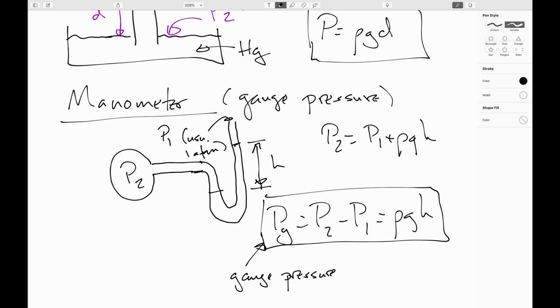Again, that's still a positive absolute pressure because it's impossible for absolute pressure to be less than 0. But what it means is the pressure inside the room is low. The absolute pressure inside the room is lower than the absolute pressure outside the room. So when you look at a manometer, it'll read a negative number. And again, it's the same deal. That way, as the medical staff go in and out of the room where the patient is located, every time they open the door, air rushes in, not out, hopefully keeping the pathogen in the room. So those are a couple applications there.